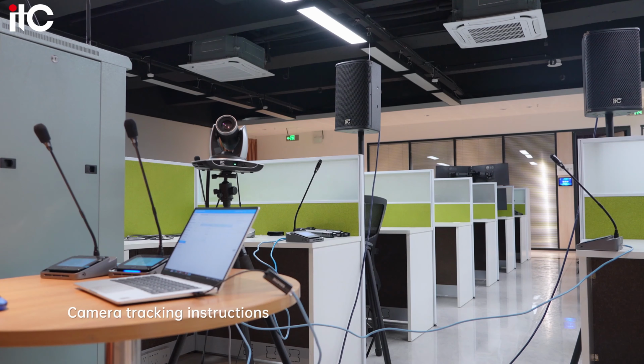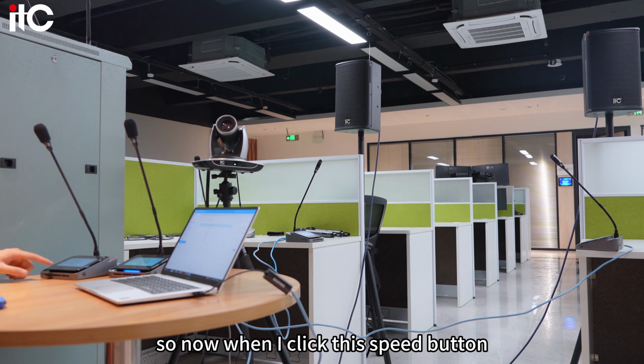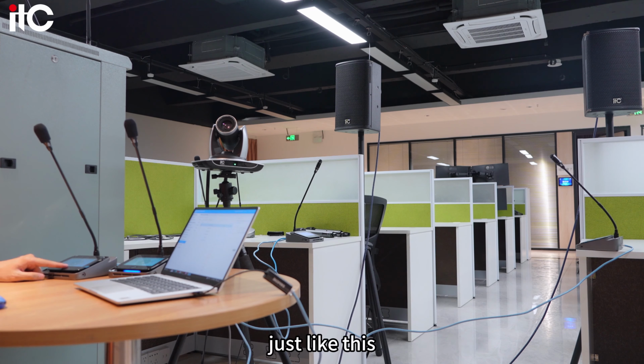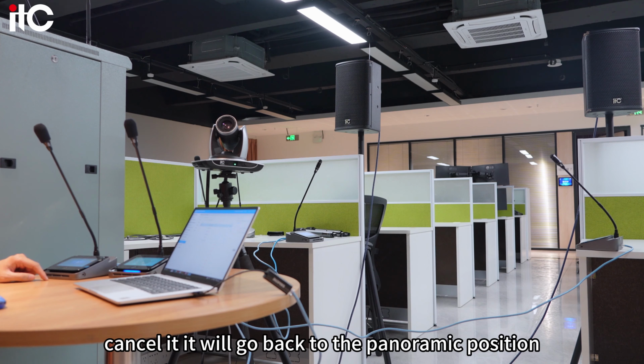So now is the effect of the camera checking system. For now, I have already set the positions of all of the microphones and also the panoramic position. So now when I click this speak button, the camera will automatically switch to the delegate units, just like this. When I press, the camera will focus on delegate 1. When I cancel it, it will go back to the panoramic position.